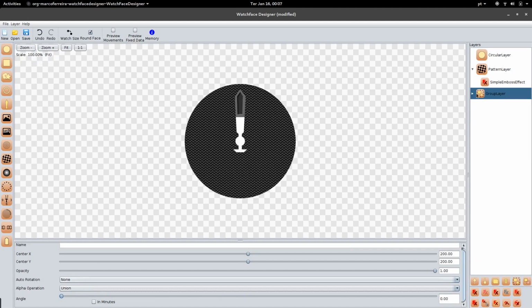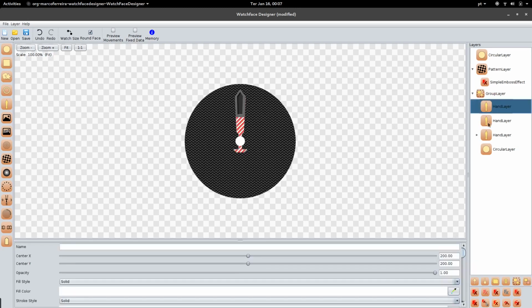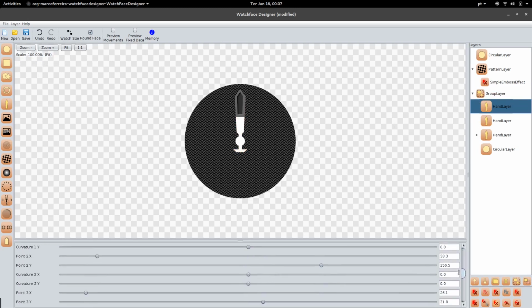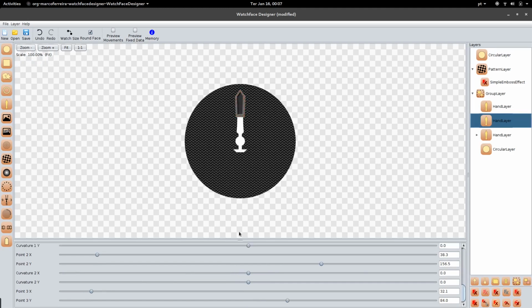And we could of course change also the appearance of the lines on the sections. Let's go back here and let's think on the second section, sorry, this one. Let's make it curvy. So we go to the second point curvature and change it. You can make it fatter or slimmer. Okay, let's suppose we want it slimmer. Okay, then we have to adapt all the others also. So let's make them slimmer, and they are not so wide.